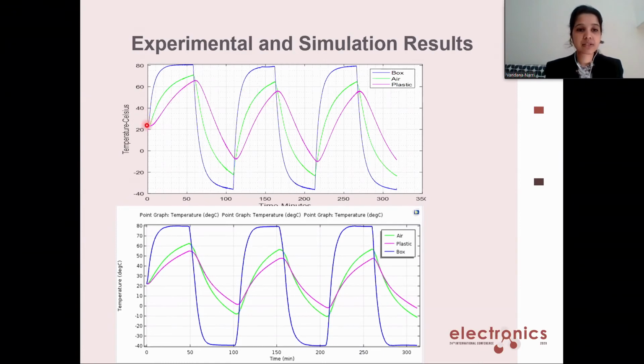We have seen that it takes almost 15 to 20 minutes to reach the stable state or the maximum stress level for the outer layer, and then it is a much slower ramp rate for reaching the minimum stress level. Even though it reaches stability, it doesn't reach the complete minimum stress level. And even though the outer layer of the component reaches the levels that we expected, the inside of the component is not as we expected. It's much lesser than what we have seen.